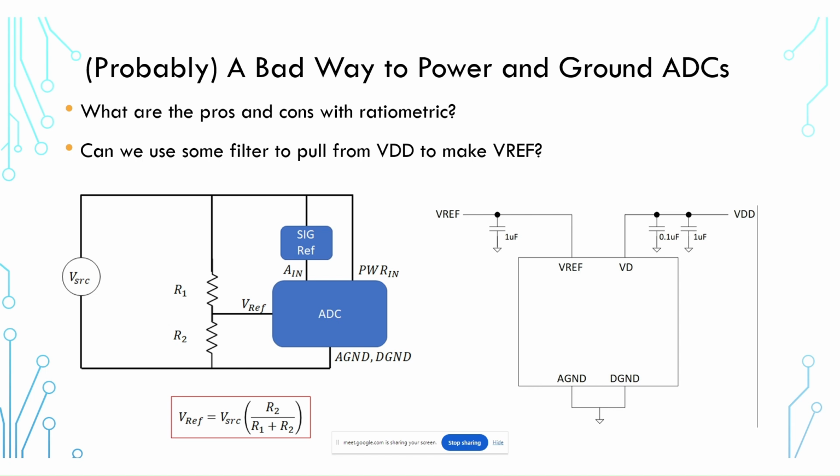Let's say your analog input signal is 100 hertz, and in one instance it's 5 volts, but then sometime later it's 3 volts. Well, you can ensure that you always use all of that dynamic range by also allowing your reference voltage to adjust by a comparable value using a voltage divider.